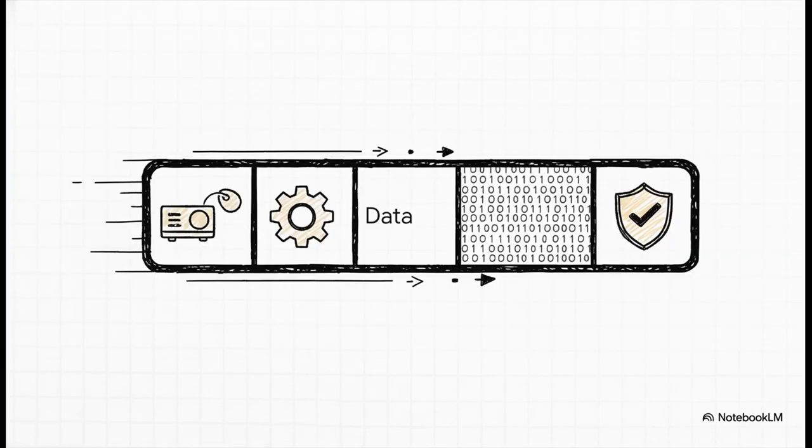Okay, so let's look at the actual message itself. It's a super efficient packet of binary data. Inside, you've got the slave's ID, a function code telling it what to do, the actual data, and, this is crucial, a 16-bit CRC checksum. Now that checksum is basically a fancy math problem that makes sure the message didn't get corrupted on its way. If the numbers don't add up correctly, the slave knows the message is bad and just tosses it out.